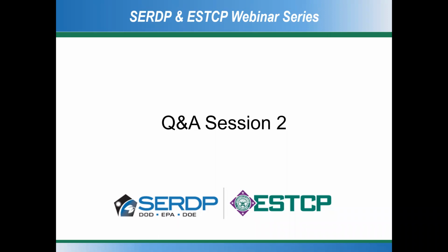I think what that could translate to in terms of the HRX well design is you might need even less treatment time, less residence time within the HRX well, which I think particularly for the active configuration where you might be pumping, the residence times in those scenarios can be quite short. So I think there's some advantages there. And of course the oxidation technology also has very fast kinetics. While you'd probably have to balance that against a replacement frequency, there may be some overall benefits to that approach. But I think, generally that's going to be a pretty site-specific analysis.